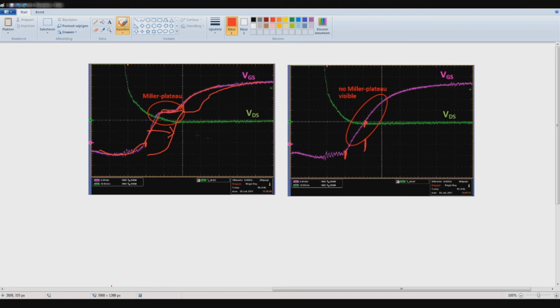So you have more time for this to happen, because if you use this same VDS over here, you still get 0 voltage switching. But here they also remove the plateau, as you can see, and you have perfect ZVS behavior,